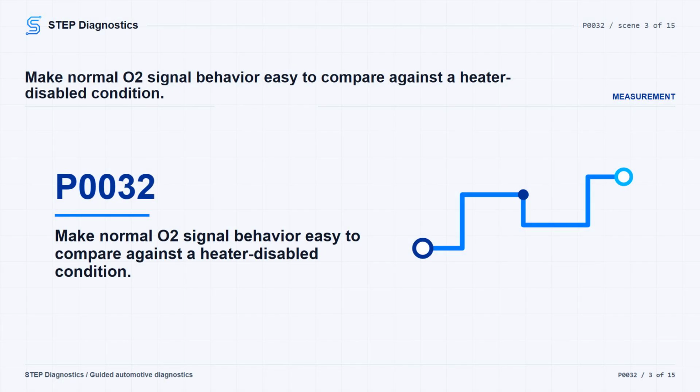Before the circuit checks, keep the sensor behavior in mind so the scan data makes sense. Normal range of the O2 sensor output is a 0 to 1.0-volt analog-to-digital, or A/D, signal. Each O2 sensor return circuit has a 2.5-volt bias, and on a normally functioning sensor, the bias signal voltage should switch between 2.5 and 3.5 volts. If the heater is disabled, the affected O2 sensor biased signal voltage can read high, usually staying above 4.0 volts.